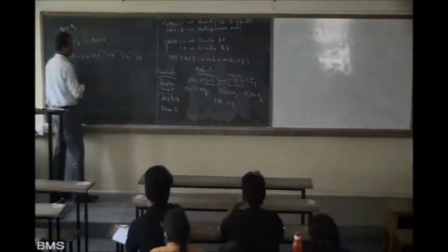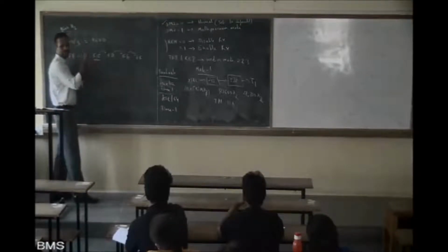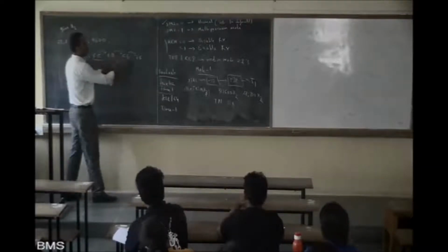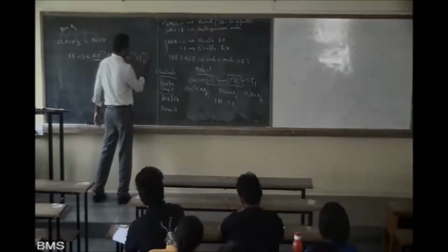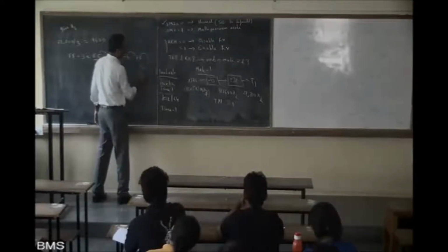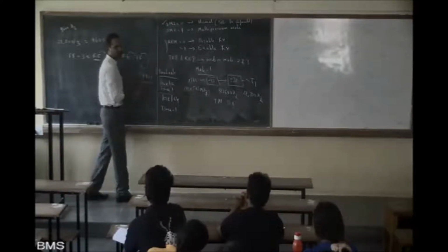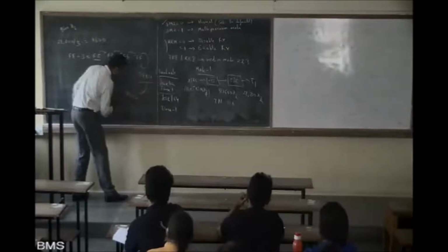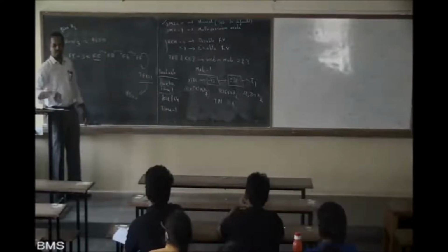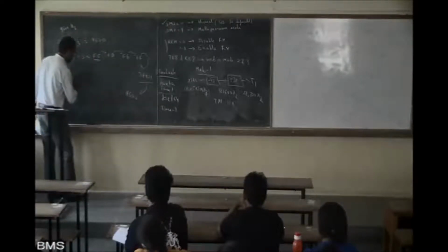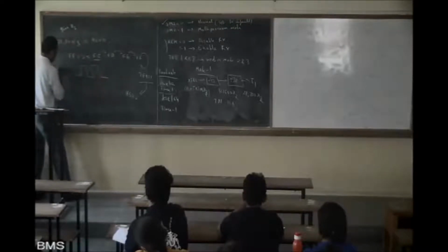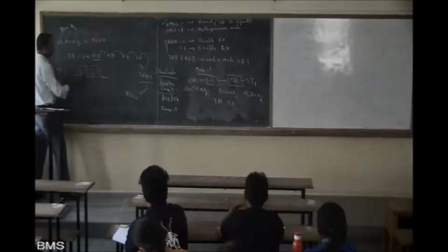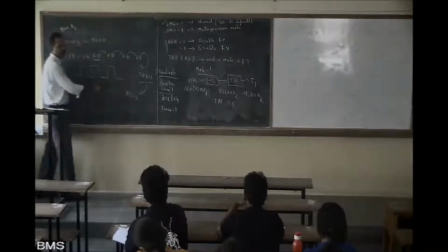So what I was saying is this. Whenever your TH value, guys listen to this. In auto reload mode, what happens? TL0 will take the TH value and counts it to FF. Once it reaches FF and overflows, it sets the TF1 flag as 1. This will generate the 9600 frequency. This will generate the square wave. If I check the TF1 signal, it will be a square wave with a frequency of 9600.